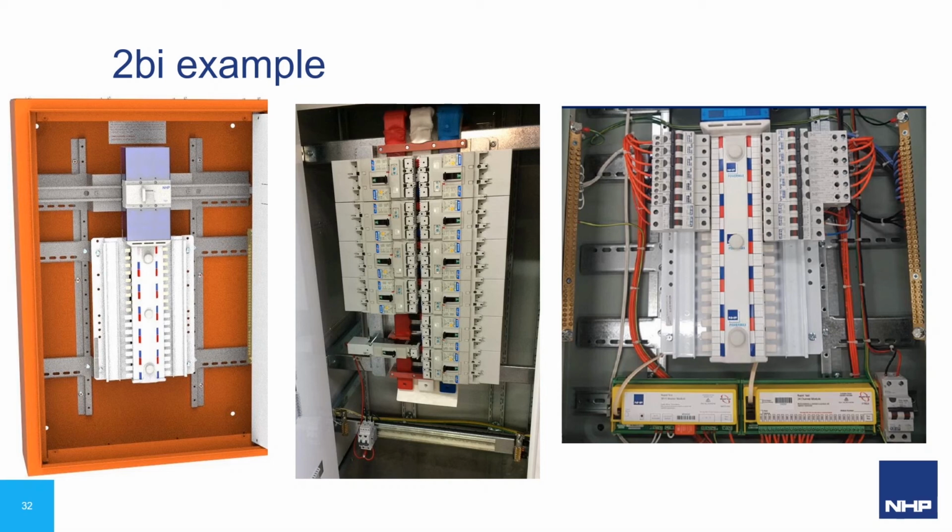Miniature circuit breakers are inherently IP2X in their designs, so there is no requirement for additional covers. If moulded case circuit breakers are used with larger terminals, then terminal covers will be required on the line side of the breaker to maintain separation from the busbar.